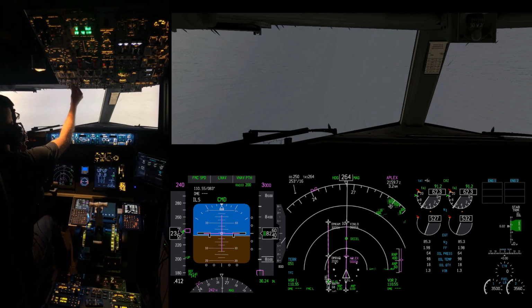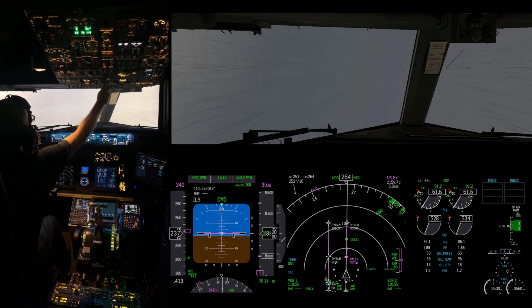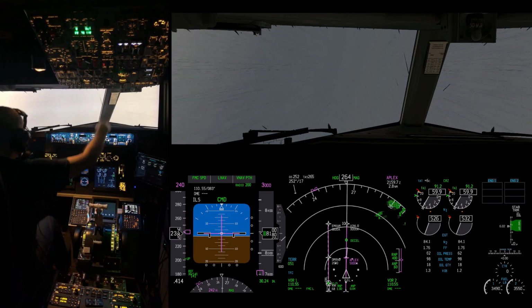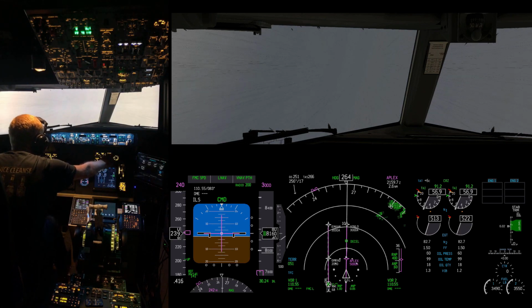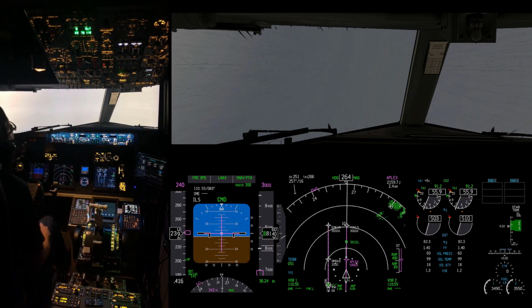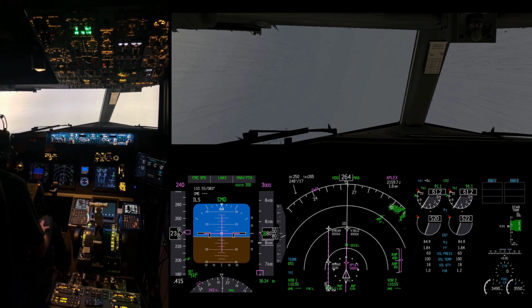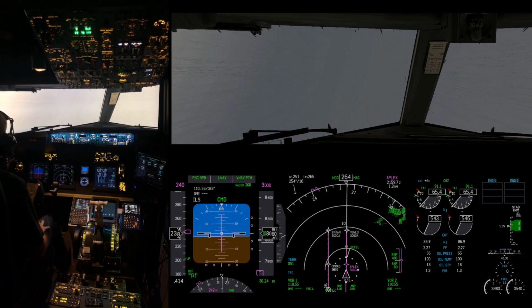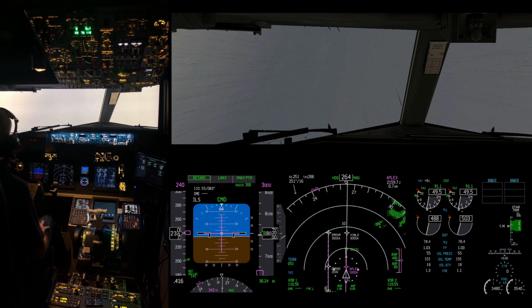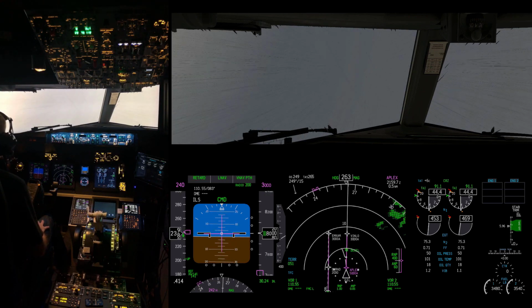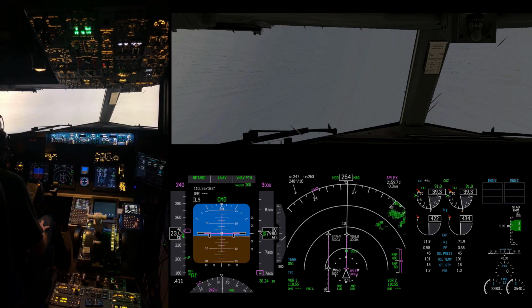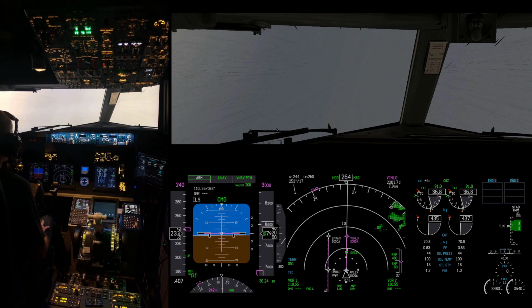Okay, we'll put our landing lights on. When we turn off lights, engine start switches to continuous. We're going to do an auto brake 3 landing. Check, we have VREF for 30 degrees of flaps is 141. Our ILS is programmed in at 110.55 with a course of 083. We have 200 feet set in our minimums, and our altimeter is 3024, which is what the current weather is in Vancouver. So we're all set for the approach.